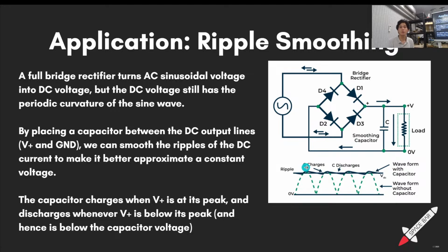And then when the voltage tries to go lower, the capacitor starts discharging. Yeah, exactly, it makes up for it. The capacitor will fill up this trough in the DC graph. Whenever we're not at peak, the capacitor discharges and it forms this slightly less bumpy DC against time wave. Does that make sense?